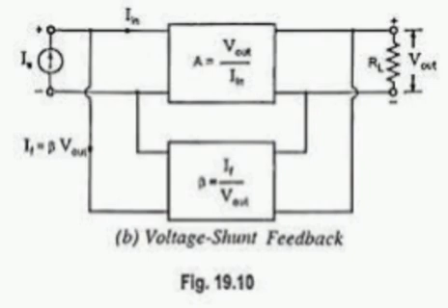Common mode voltage gain ACM equals Vout by VinCM, equal to minus RC by... numerator part is RC minus RC, denominator part is re plus 2RE, small re plus capital 2RE, giving minus RC by 2RE, since capital RE is far greater than small re. CMRR equals modulus of A by modulus of ACM, where A means differential mode gain and ACM is common mode gain. CMRR equals differential mode gain by common mode gain, that equals 2 gm RE.